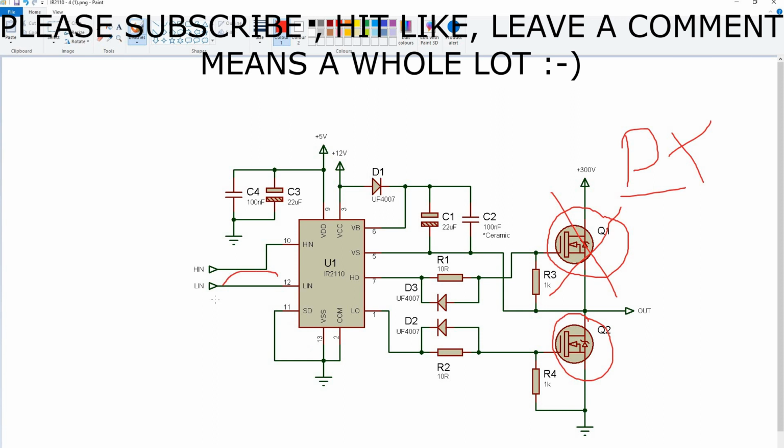These are just decoupling capacitors here. These just keep the logic supply voltage very clean with minimal amount of noise. So the 5 volts here is just dictating that you want 5 volt logic signals going in. Not exactly that, but anyway.